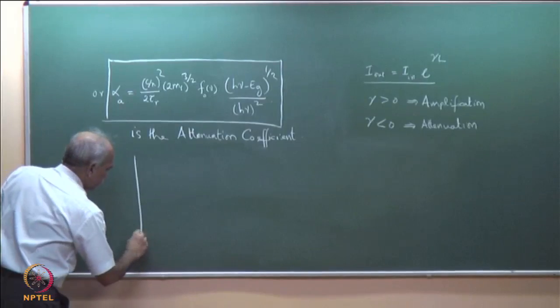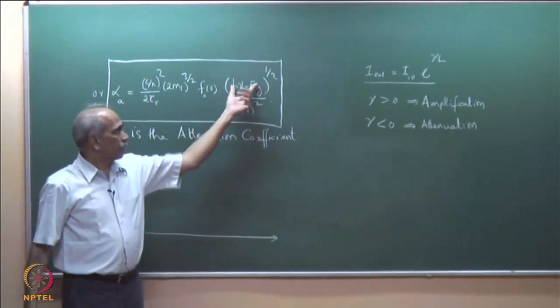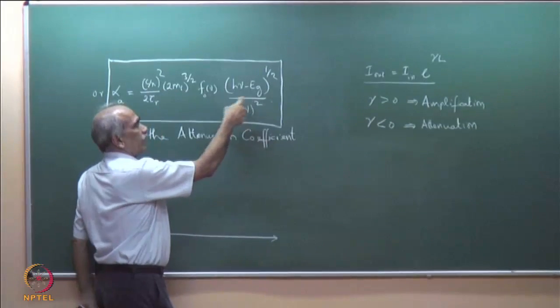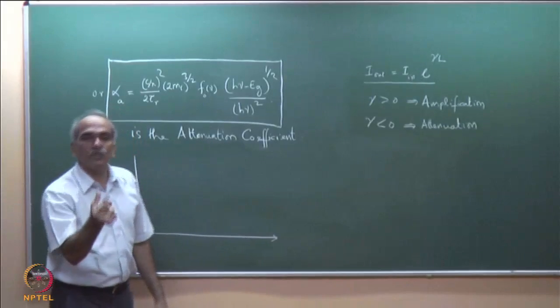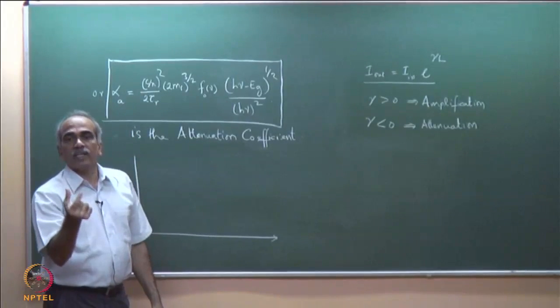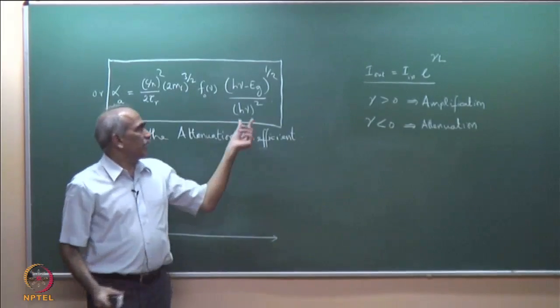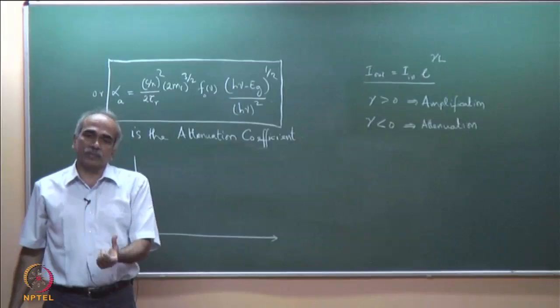So, if I plot this, earlier also we had a similar expression here, and I had said that h nu square variation is very small in the range of interest. In the range of interest was the bandwidth of the amplifier, which was only 10 to the power of 13 hertz, and therefore, that is a small fraction of light frequency.